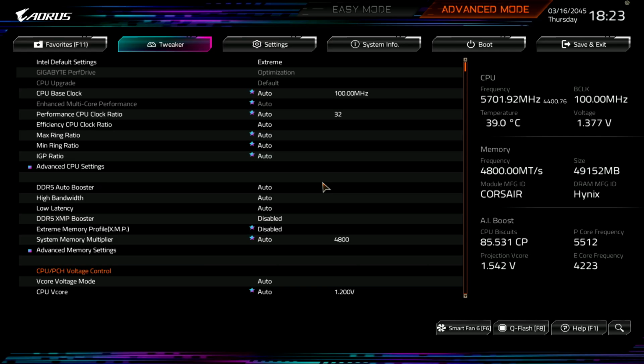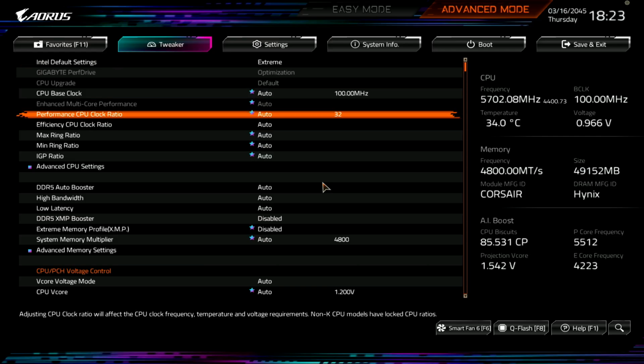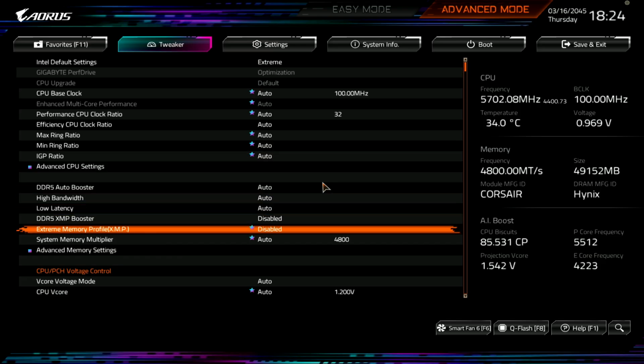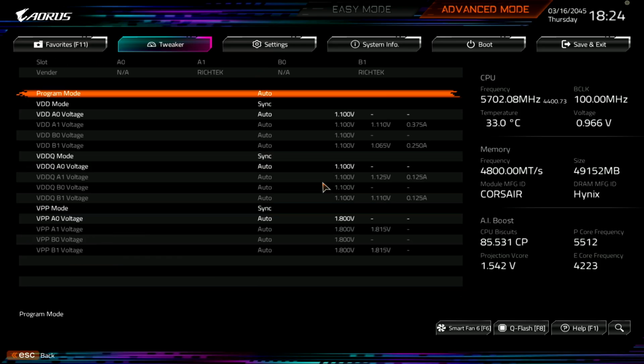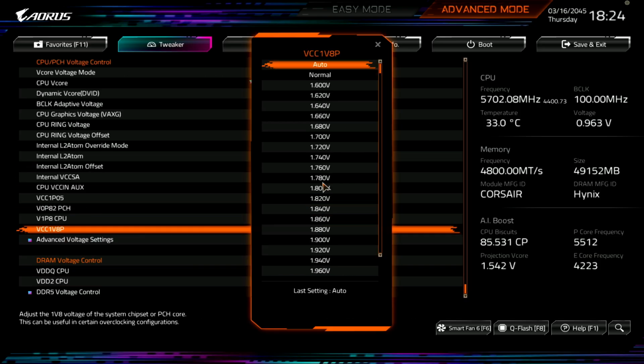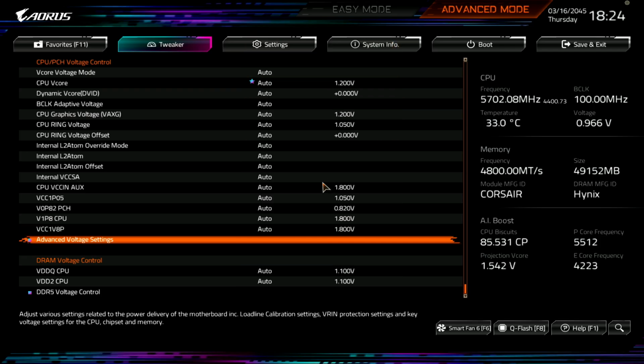And if you have an Asus motherboard, you might have the option to have the VRM load line synchronized to the AC load line automatically. Actually, it goes backwards. I think you set your VRM load line and then the AC load line setting gets synchronized to that. But anyway, if you're on other motherboards, you're basically going to have to figure it out.